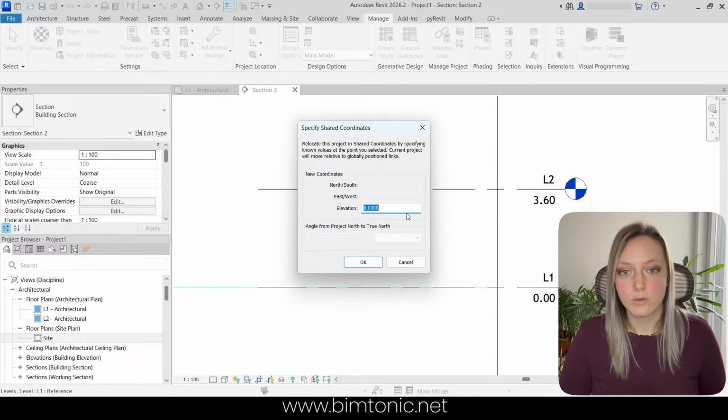What I first have to note is to also mind the units because I have turned my file back to meters, so I can simply insert the exact height that I saw on that plan. But if your files are, for example, in centimeters, you have to insert this number in centimeters, basically convert it to the units you are using in the model.